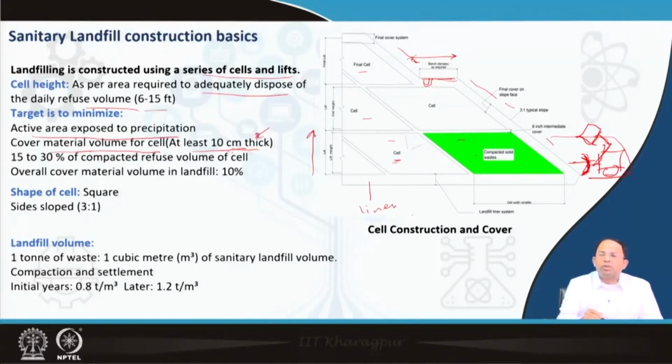And based on this volume of soil, which is available on site, or we have to transport it from somewhere else, we can even think about what sort of waste can be stored in this particular landfill. If I have to import soil from further away, the cost would be exorbitant. So maybe the life of the landfill would be less, right? So it is based on this amount of soil which is available on site, right? And if we import soil, then automatically the cost increases. So at one point, the entire operation may become infeasible, right?